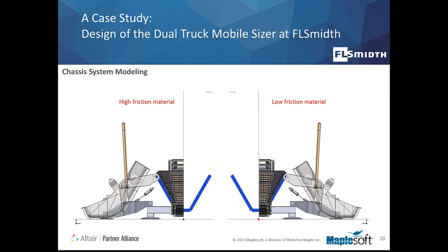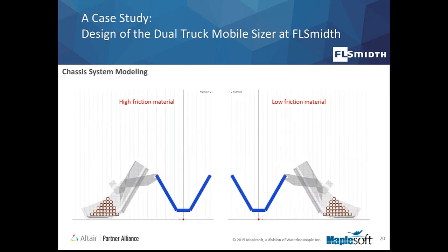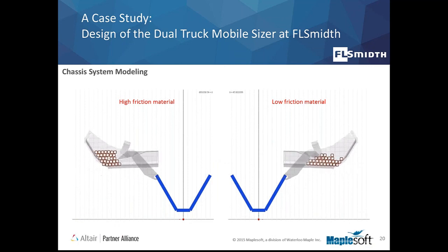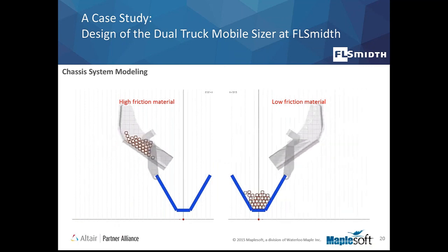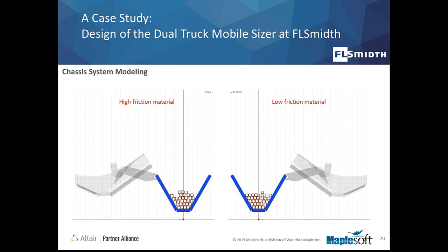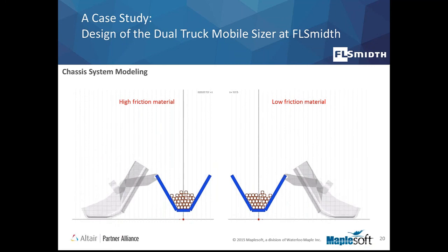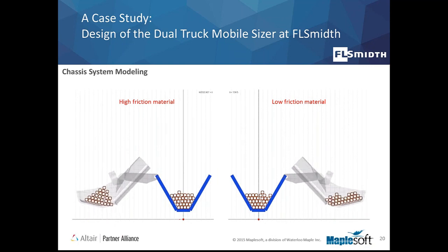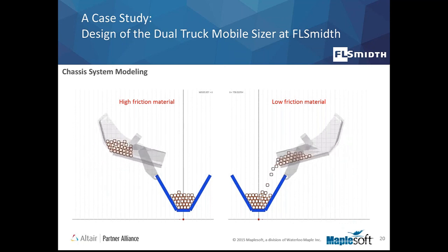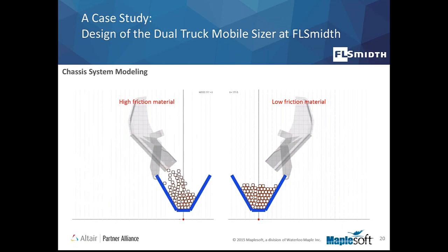Using the base model that we had, we were also able to answer the question of what would be the impact loading on the hopper as the skips dump their content onto the hopper. And we have created, in the same environment as the base model, specialized extensions to the model that incorporate the flow of material in a simplified, discretized way, and are able to measure the impact force over the duration that the material is flowing into the hopper.